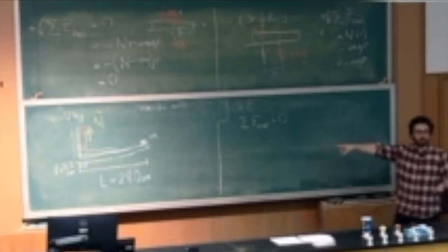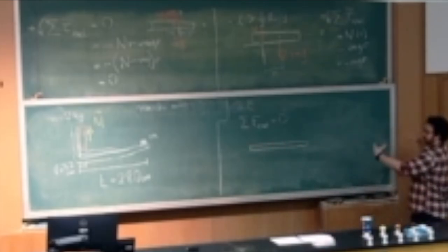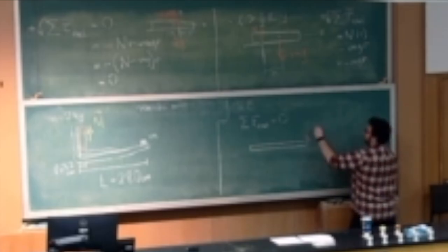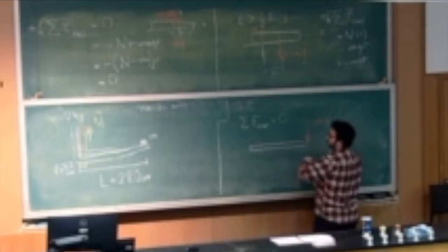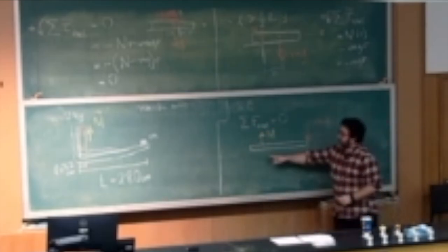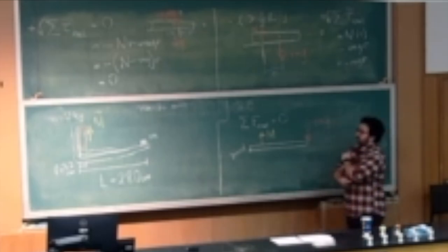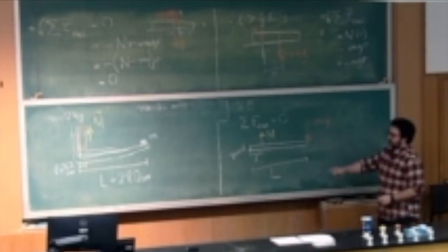So we need to isolate this picture so that we can draw some free body diagram, right? So this is how we do it. We will assume this beam structure for our arm, and at the very end, at the tip, we have this mass. We have the weight of the mass, m times g. Easy. Then for this capital M force, the force that the muscle group will experience, we have this upward force, capital M, and this is the pivot point for all of our discussions, which is simply this elbow joint. Okay, this is known, lowercase l, this is known, capital L, and the values are over here.